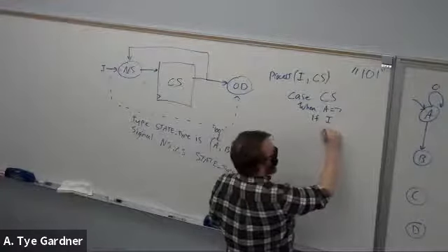But in digital logic, technically what's happening is else don't care. If you don't write the elses, it's otherwise don't care. Most of the time it will do what you think; it'll just keep the same value. Sometimes it doesn't, and it can be really awful to debug. So in VHDL, generally speaking, it's best to enumerate all options, meaning end with an else. All right, that's all.